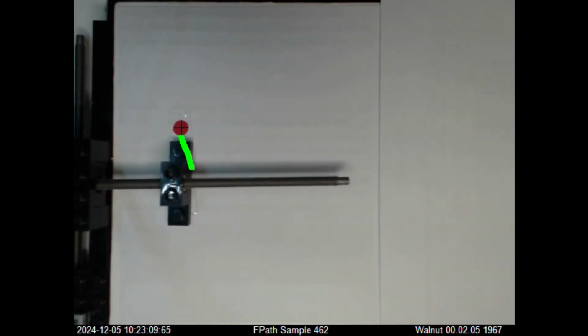The red circle moves to the nearest green point. As soon as it moves over it, the green point is rendered transparent, ceases to exist, and the software immediately chooses a new green point. Doing this continuously moves the red circle along the path. The line gets followed. The beauty of closed-loop control. What is going on here is essentially Stigmergy. Stigmergy is the modification of the environment to communicate information, and it is a well-known phenomenon in behavioral biology. Since we are dealing with computers, video, and mechanical control, I've named the overall concept Graphical Stigmergy, and we can call the specific case we have just seen Stigmergic Path Following.